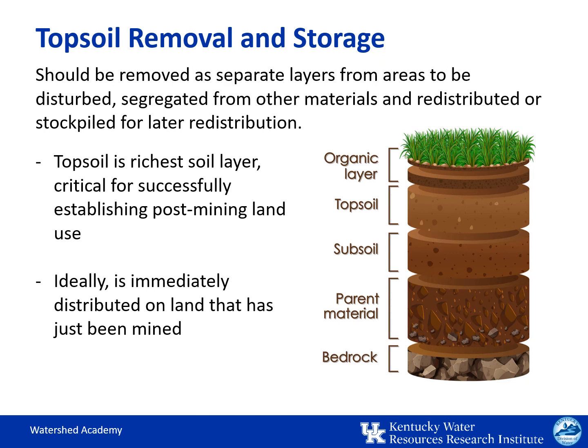Ideally, topsoil that is removed from an area of an advanced mining cut should be immediately distributed on land that's already mined. If it must be stockpiled, measures should be taken to stabilize the piles and minimize erosion. For stockpiles left in place for more than 30 days, the establishment of quick-growing annual or perennial vegetation is required.